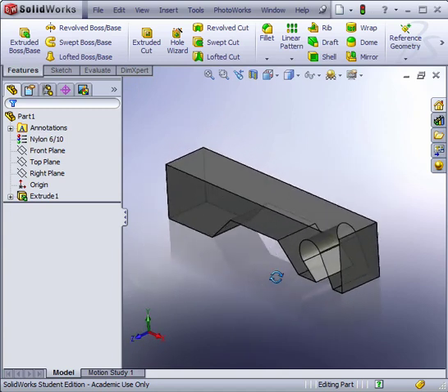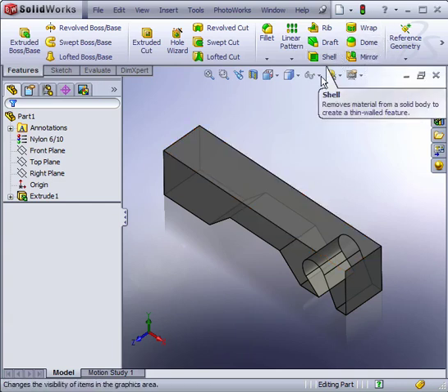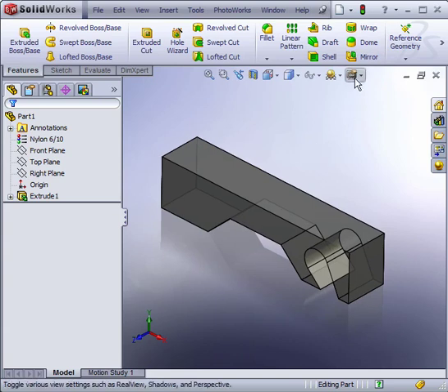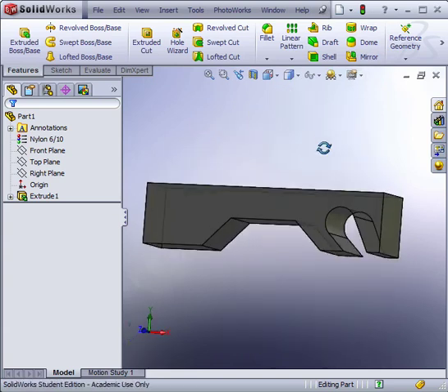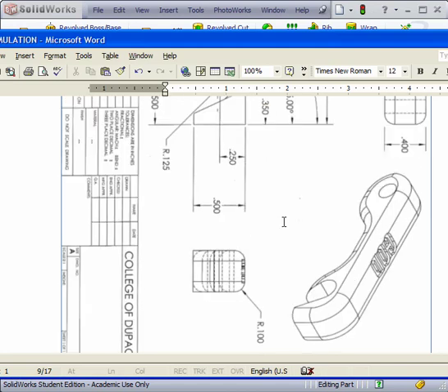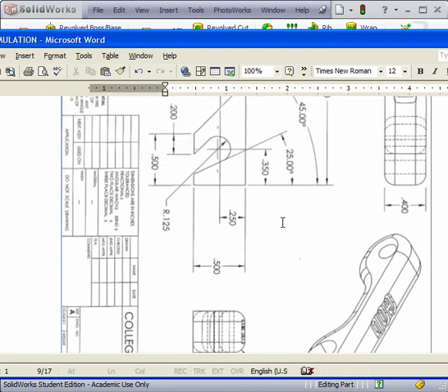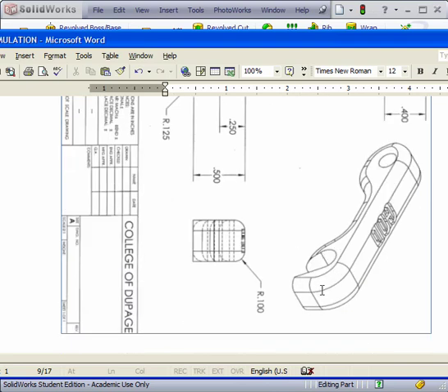Alright, you can see there's some transparency associated with the nylon material that we selected. That's alright. We could actually disable that as well, or change this type of view setting, but we could go ahead and stick with that. That's fine. The radii on here, we could actually add them if we want. We could keep a simplified version like this, which was actually perfect for finite element analysis. Any inside radii generally you do want to keep. Any outside radii, such as what we see here, it's not necessary, these 0.1s.